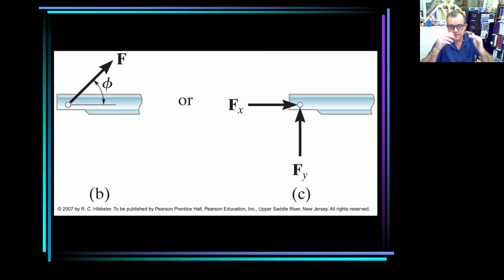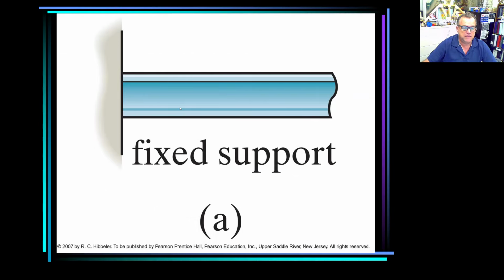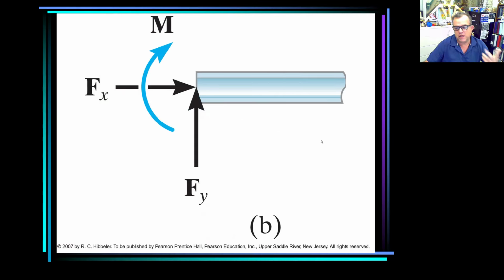It doesn't have to be horizontal and vertical. However, it's easier for me and for you probably to calculate the reactions in that way. But sometimes if you have an inclined axis of reference, well, you can put them inclined also. You can put it inclined like that. Or 1 with a known line of action. A fixed support, 3. What 3? And remember, we are talking about 2D. What 3? 2 forces and 1 moment, or 1 force with a known line of action and a moment.